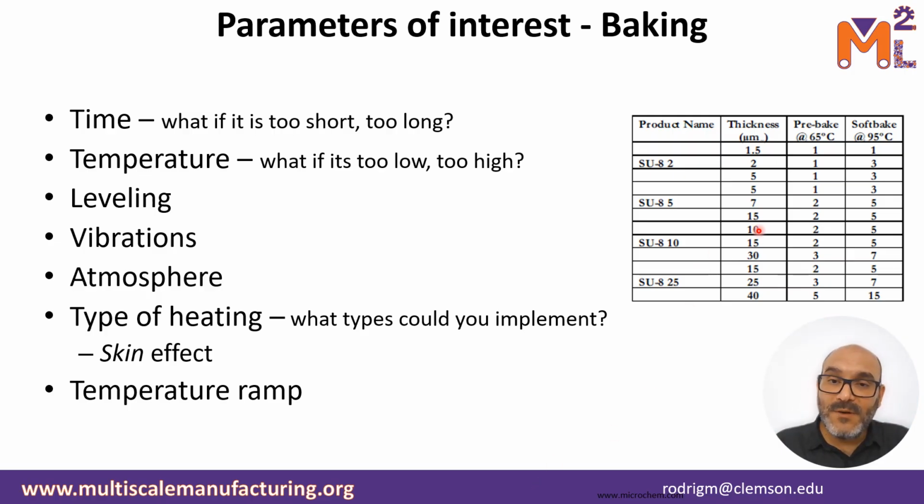This particular table shows you some guidelines on the kind of pre-bake, the soft-bake times that you can expect. All of these tables that are shown here, you can actually find them in the processing data sheet of the SU8 formulation that you're using. All the providers will provide you with the processing data sheet.